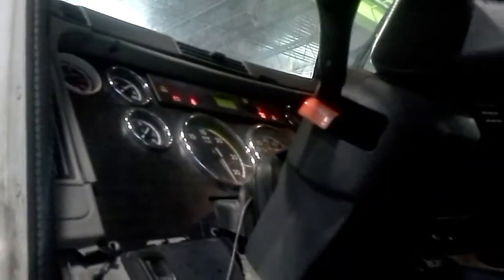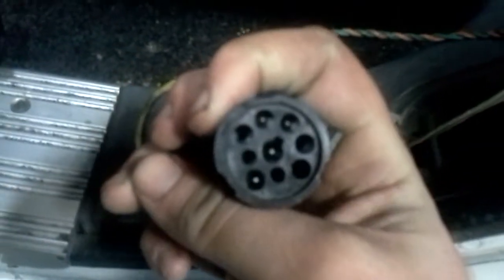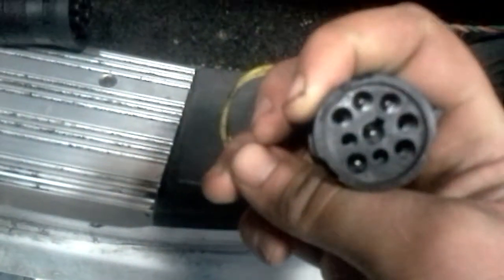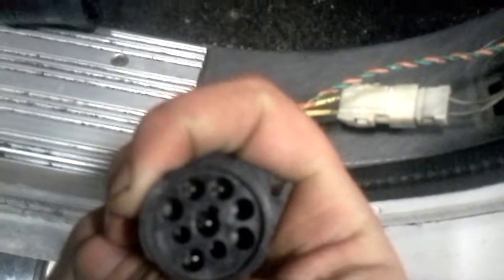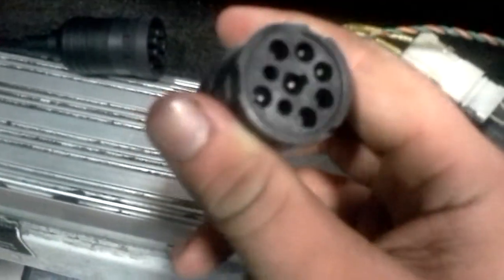Okay. Basically what you want to do is start off with the key on. Go ahead, flip the key on, dash lights up. Now, real quick, I want to show you guys something. On this plug, way down in here, this is the plug for the actual truck itself. Some of these pins are not being used. That doesn't really mean anything, but one thing I wanted to point out was that sometimes when you plug your diagnostic troubleshooting code reader into this plug, you can get somewhat of a connection error.